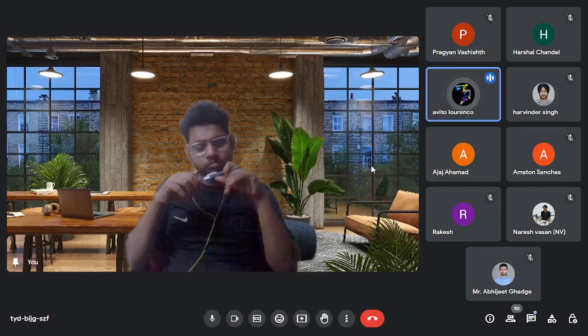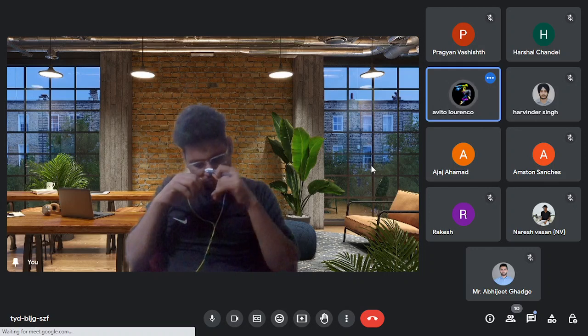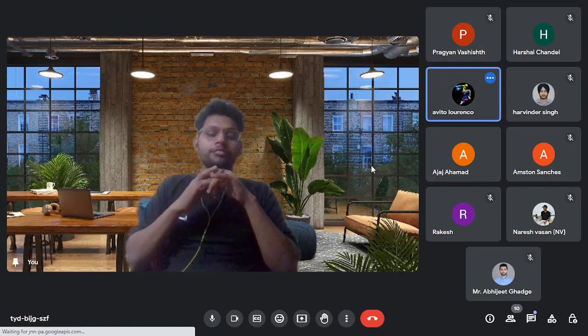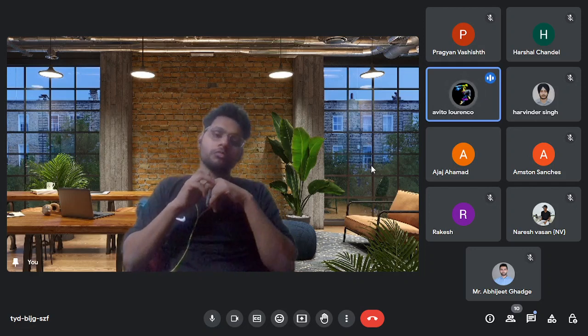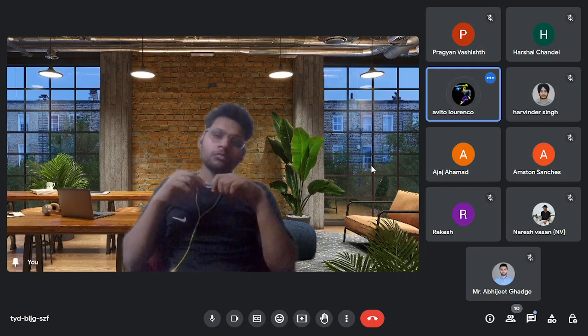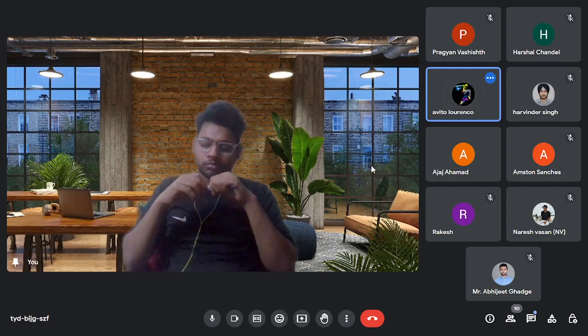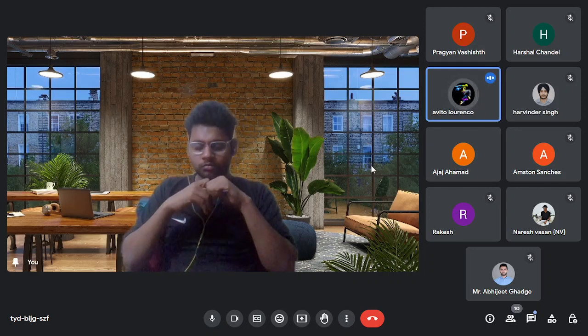So this is going slightly deeper, where we ask how that pipe broke. Was the pipe getting rusty, or did it have some kind of weak spot, or did it weaken over time, or was there some blockage? Once the pipes carrying the high pressure air break, they will send this high pressure air, let's say 30 bars, into the water which is flowing at 1 or 2 bars. Your intercooler casing is not meant to sustain 30 bar pressure, so it could explode the entire thing. To avoid this large explosion, we have the bursting disc.